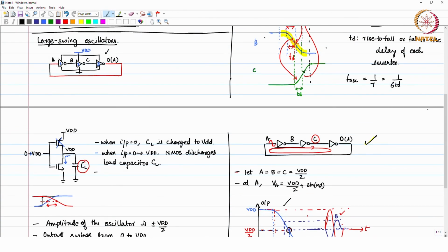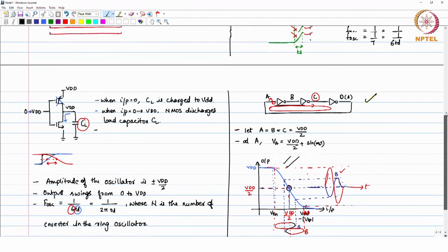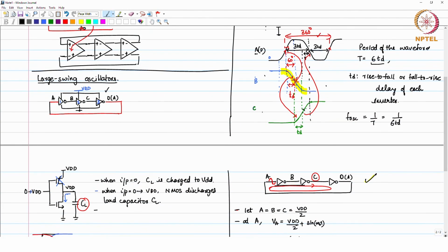When your MOSFET goes into cutoff region, the linear gain characteristics cannot be applied, but for the oscillations to build up, that is required. Once the oscillations build up and reach 0 and VDD, you get the fixed swing oscillations, and they will be sustained if and only if you have the delay like this. If somehow the delay is not maintained, then you will not have the oscillations.